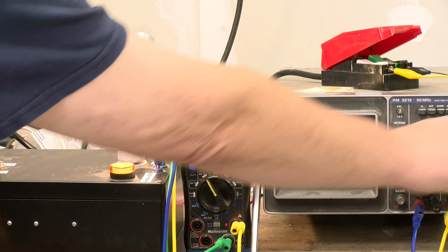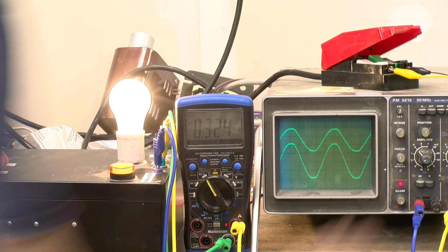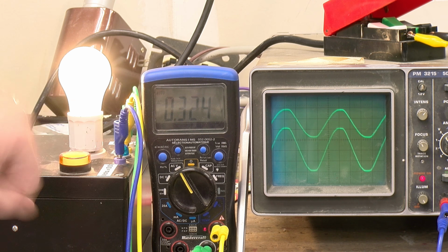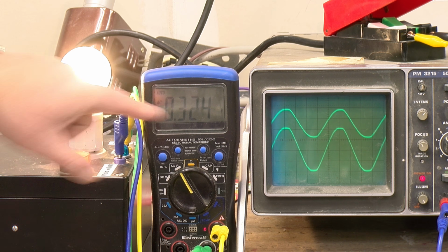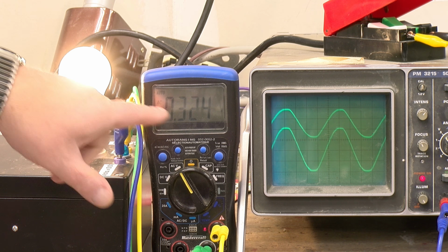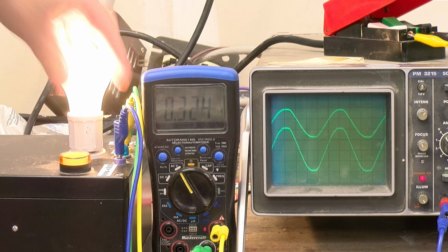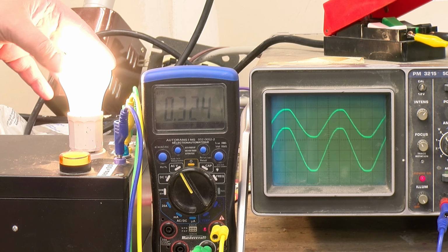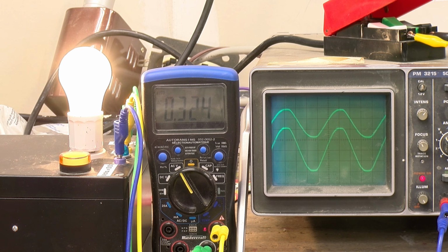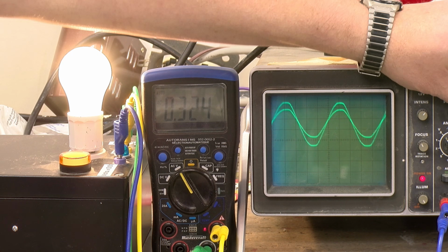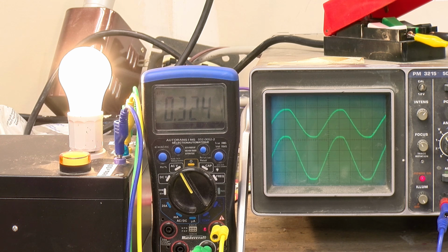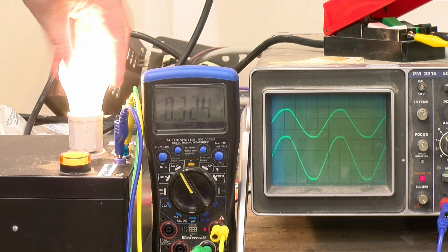And here we go. There's the current. We can see it quite nicely, and we can look at our voltmeter and see in this case the voltage maps directly to current. So we have about 0.32 amps flowing through the light bulb. That's what we'd expect for a 40-watt bulb. This is the type of bulb you get in an oven or a refrigerator. And yes, you can certainly see these things line up quite nicely, a power factor of 1. Do you think we're going to see anything that good again? Probably not.